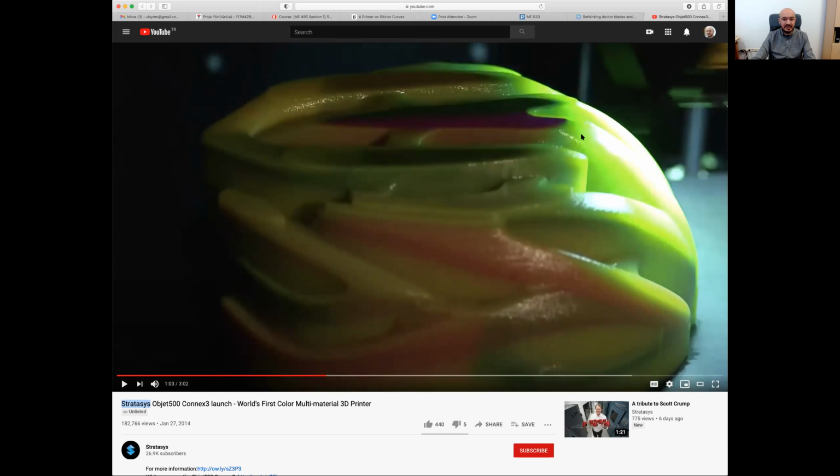While it's going, you can see some light, right? Which means that they are jetting some kind of photopolymer. And while they are jetting it, they also do polymerization with the help of this UV light. But these things happen in less than a second. This polymerization happens in a very fast way.